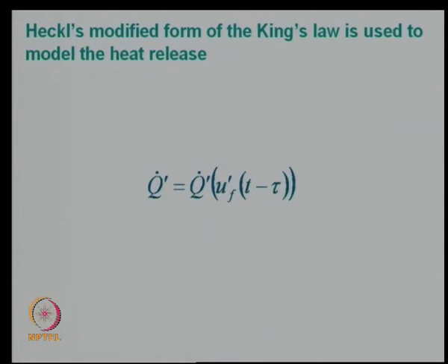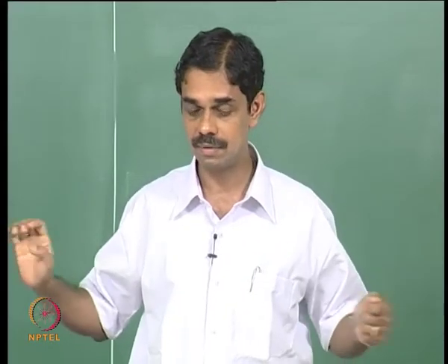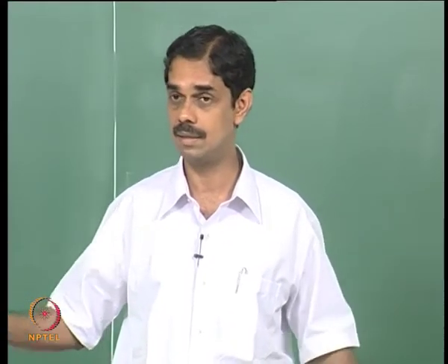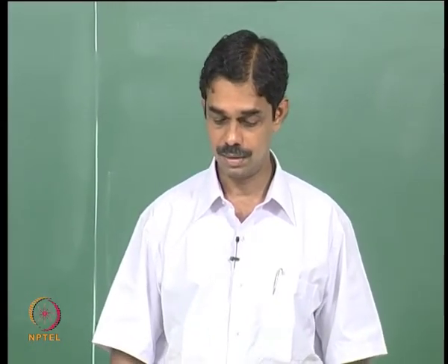Now you do not have to do this, you can actually use CFD to solve the flow around the cylinder and calculate the heat release rate from those calculations, which is quite involved, but I wanted to keep this as a toy problem, a very simple problem. That is the reason I take this approach, and this is the correlation given by Heckl. We did this, in fact we even linearized it in class and derived a linearized operator.